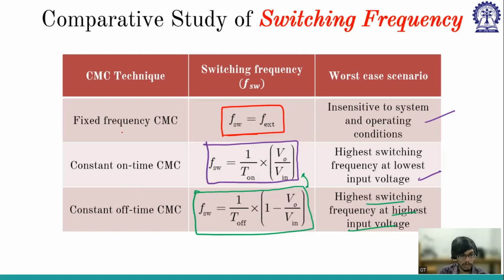Majority of products use voltage mode control with fixed frequency, or current mode control, or constant on time. Constant on time is a very popular control technique used in many products, and constant off time also.